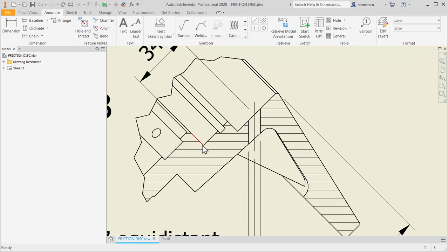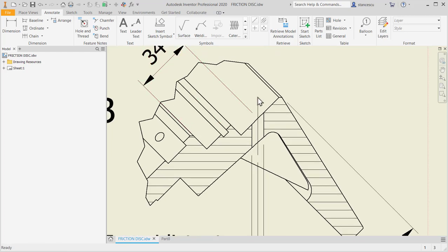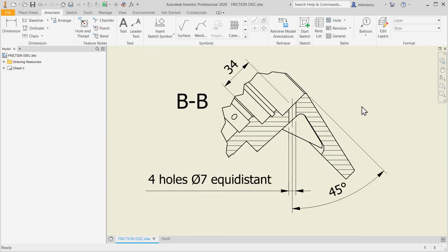So I draw this line, I place a point on this face, I dimension it at 34, and then I'll select the point of intersection between these two to start the hole and to have all the possibility to drill this hole. You see immediately what is the solution. 45, diameter of 7.